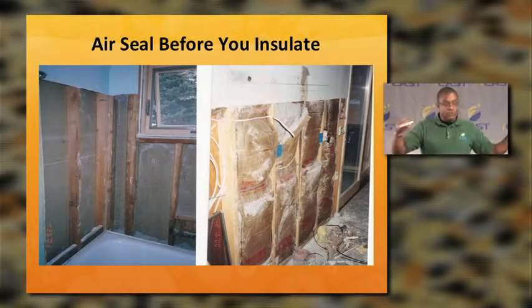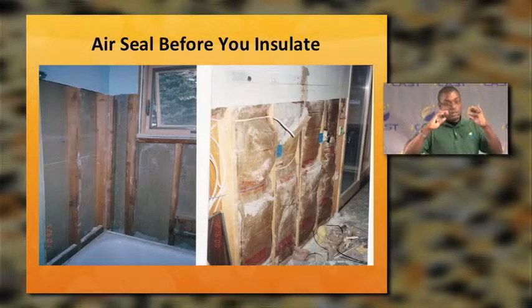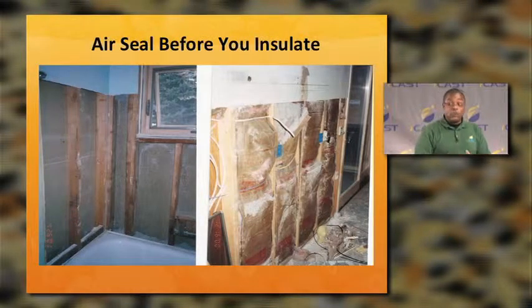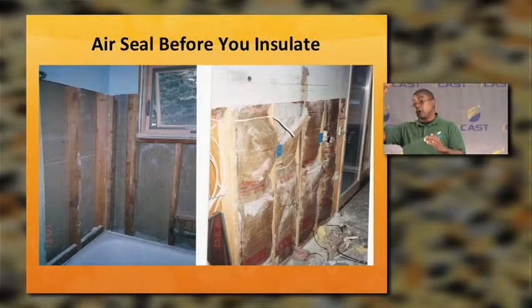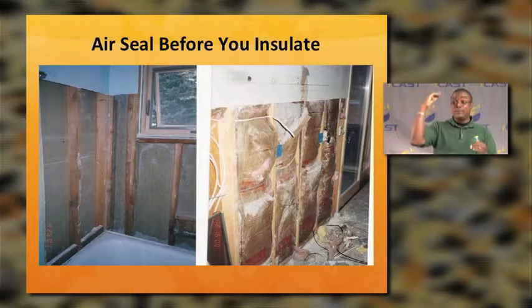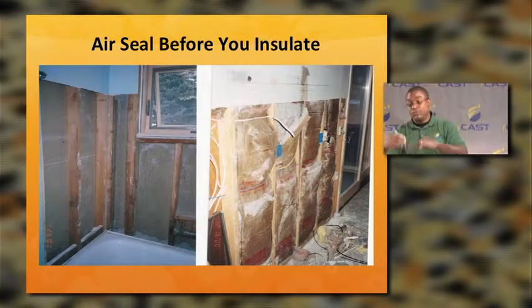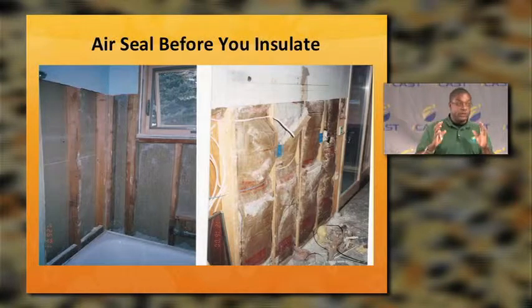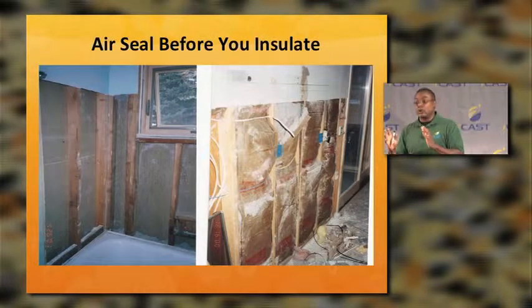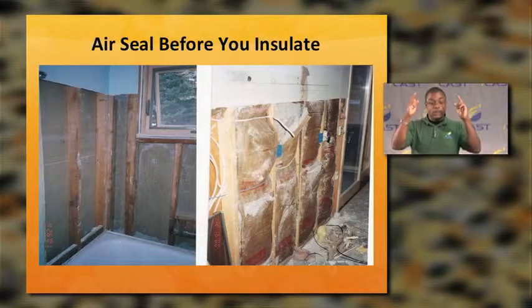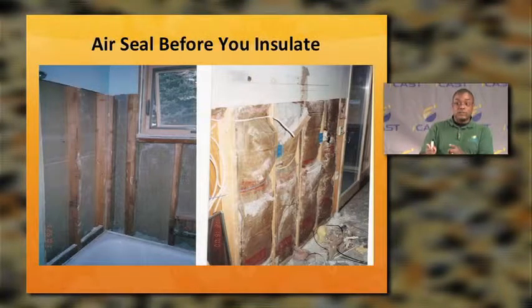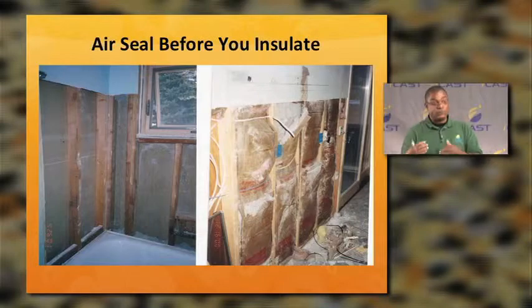You've got to go through, dig through insulation. If there was R11 there before and we put R38 now, you're going to have even more insulation to dig through in order to air seal. So we want to make sure that we emphasize to our homeowners that we want to air seal, then insulate. So if their job calls for insulation, make sure that air sealing gets done first.